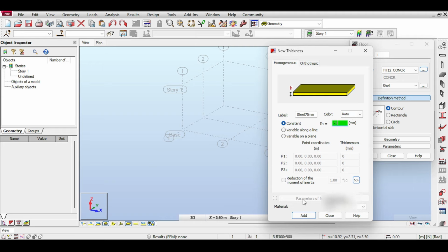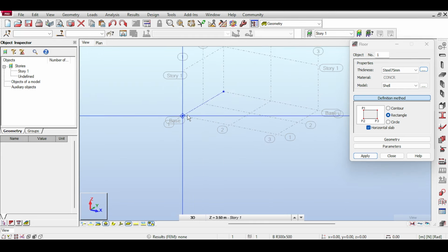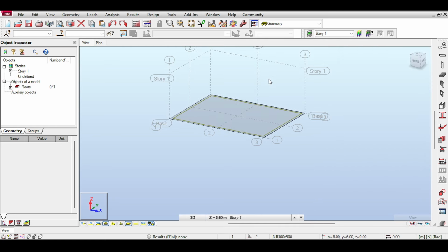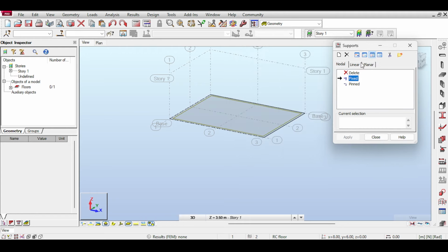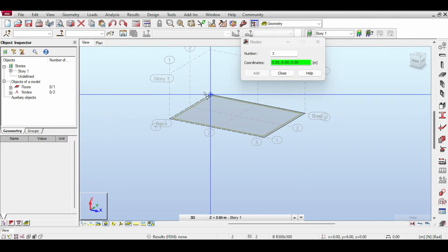Now, I want to mention something very important about steel plates. If you plan to have a steel plate that covers a span, then you will be surprised how thin your steel plate might be and still be acceptable in a code. However, a pitfall in those plates is that they vibrate. You don't only need to check if the plate is good in shear, moment, stress and axial, you also have to check its vibration capabilities and how it would vibrate under transient foot loads. Anyway, for now, I just want to talk about the stresses.